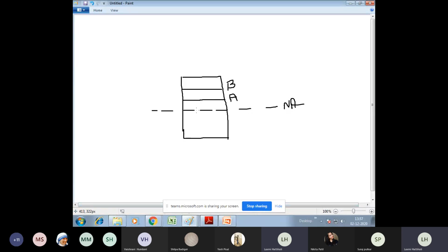And where is the bending stress minimum? At point A, ma'am. Okay, forget A and B now. In general, in this particular diagram, where is the bending stress minimum? Ma'am, at the neutral axis point. At the neutral axis, right? Very correct. So please remember these concepts. With all these basics, we'll continue with the numerical examples in the next class.